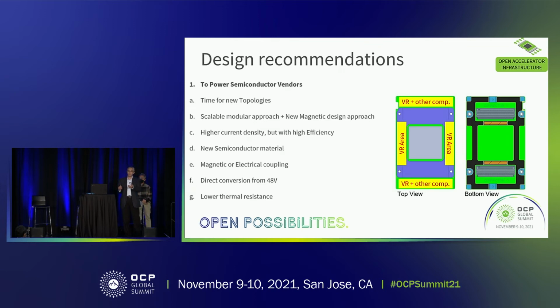And with high thermal resistance and a lot of power dissipation per component, thermal teams say, okay, we cannot cool it. Yes, you can deliver high current density, but we cannot cool it. And many times thermal team shuts down solutions because they cannot cool it, because the thermal resistance is very high. Vendors and power semiconductors say, oh, we deliver to you the power density you're looking for, but I cannot cool it. So thermal is a huge factor. Thermal resistance is a big, big, big factor. It's a challenge everywhere, mechanically, thermally, electrically, everywhere it's a challenge to us.